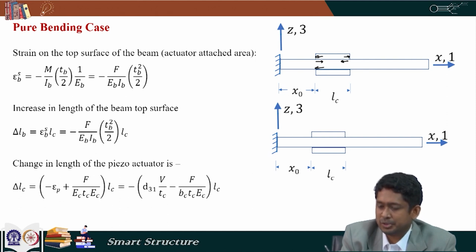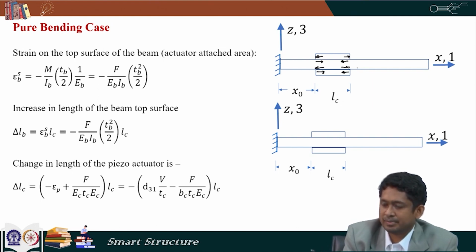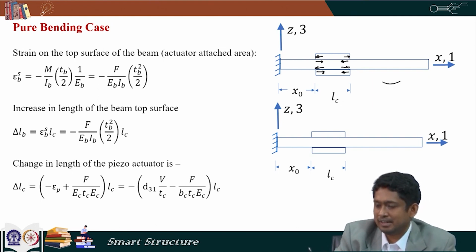On the other hand, because the actuation is opposite, the bottom part of the beam will experience a tensile force and the bottom piezo would experience a compressive force, and that would give rise to a bending in this fashion.